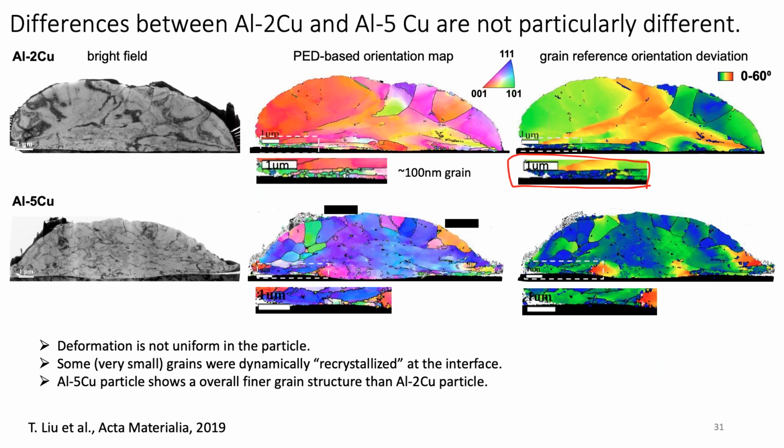However, when you do laser assisted cold spray, when you go to those highest temperatures, like 900 degrees C plus, we have seen some local oxidation in that regard. Not so much during the impact event, but when the nozzle moves away from the material, it has a few seconds or tens of seconds to oxidize, and now you're kind of depositing back on that. So for those that want to do laser assisted cold spray, you'd want to be mindful about oxidation, particularly for oxidation prone materials.